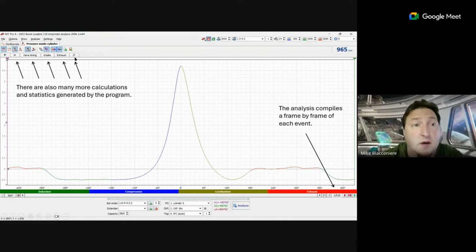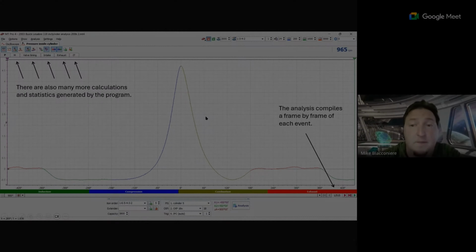Then it also maps your ignition timing in a 3D map, which I don't think many people are going to use. If you're doing reverse engineering or custom tuning, it would be handy, but otherwise, it's also kind of nice for just distributor setups. I've done a few where I just want to make sure the distributor curve is doing what I expect it to do, and this does a really nice job of that.